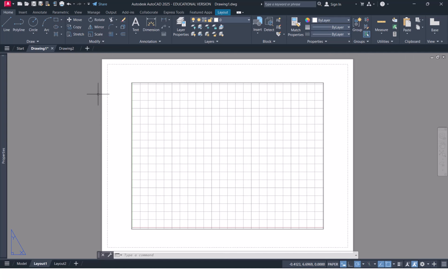In architectural drafting, we'll do just about everything in model space. So we'll dimension in model space, we'll do text in model space. The only thing that would go into paper space would be general notes, like a block of text.